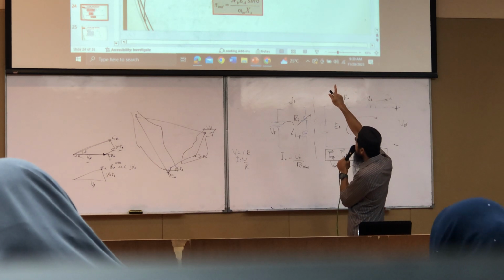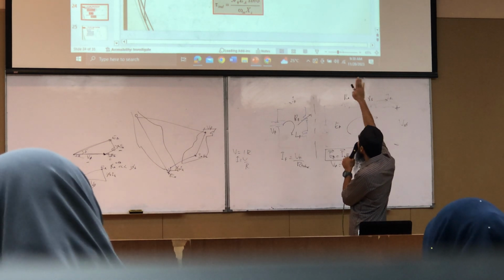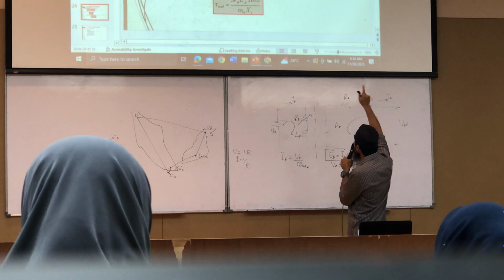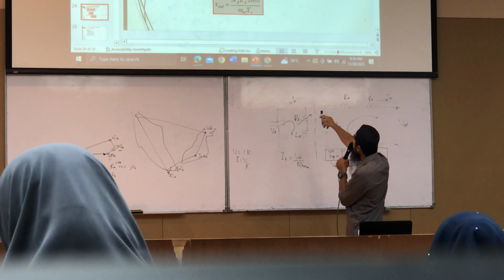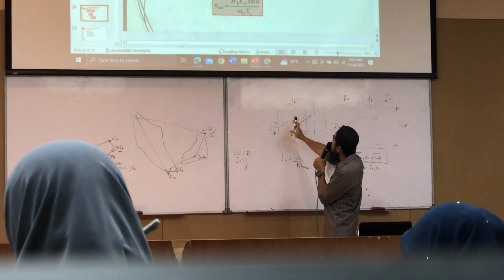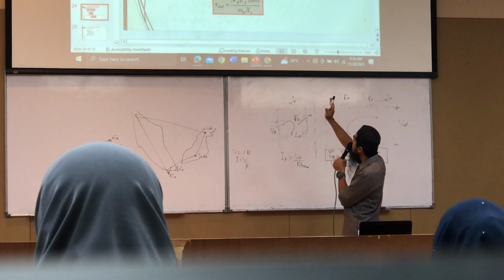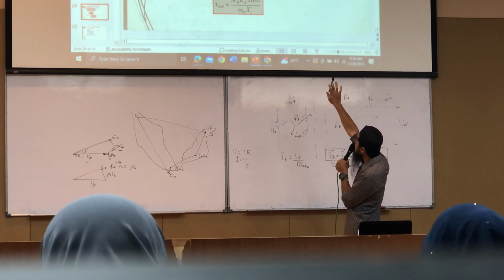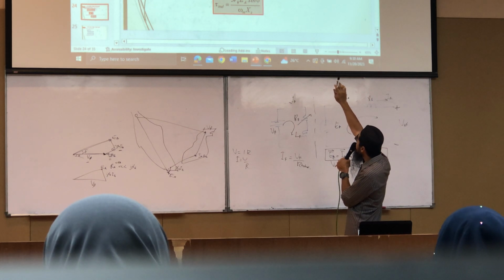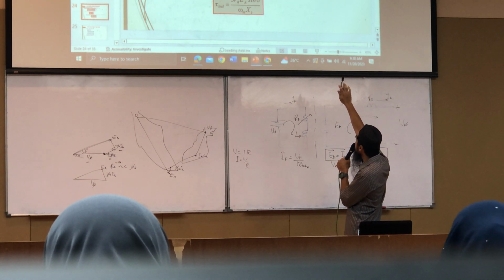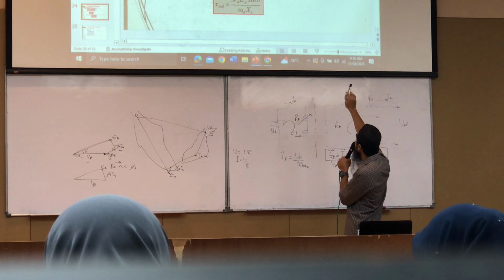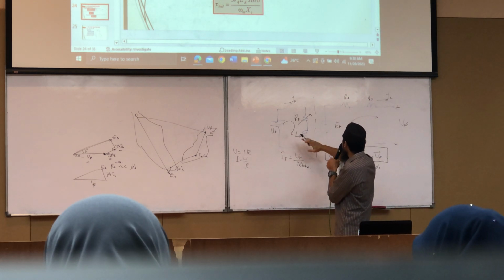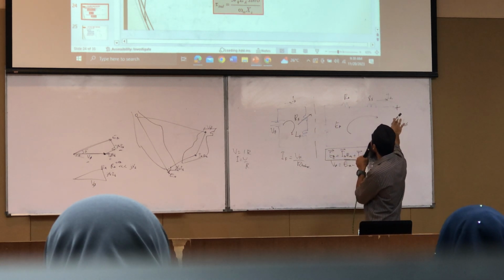Output is mechanical, output power is electrical. P in, our part here, it consume, or they have a loss on the stray, friction and the core. And after it jumps to electrical part, the losses will be I square R or electrical.